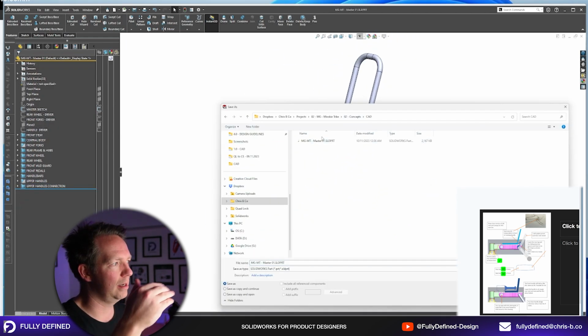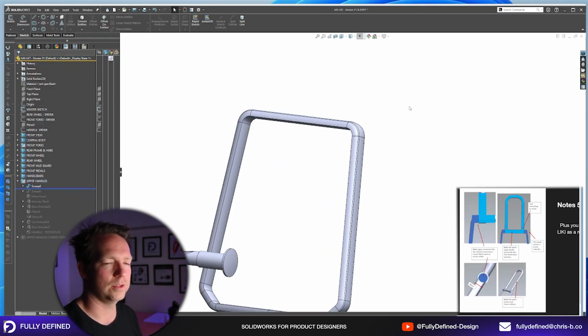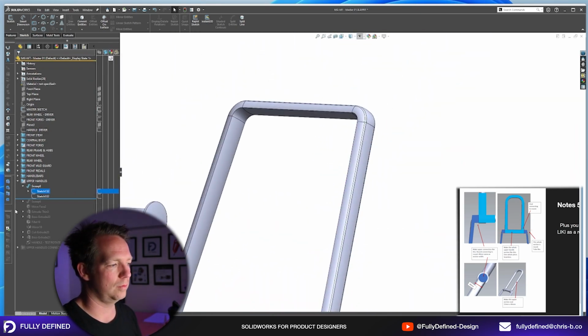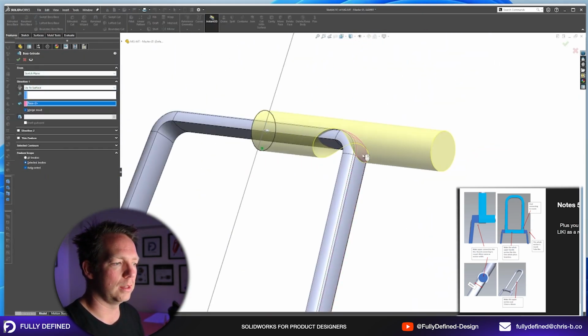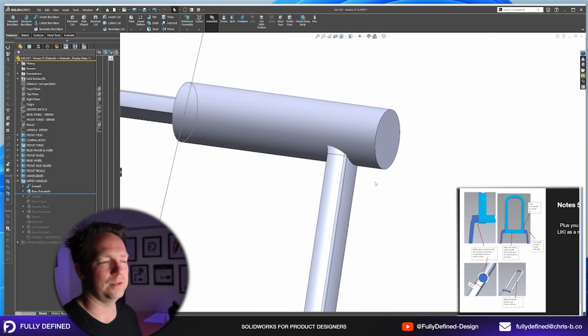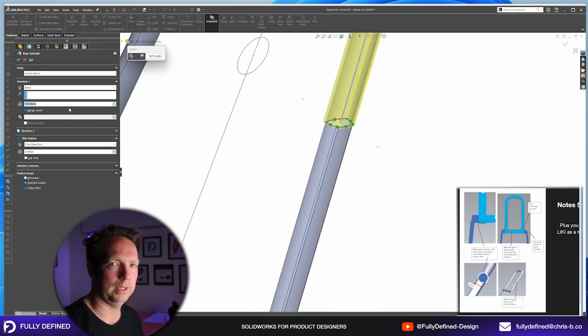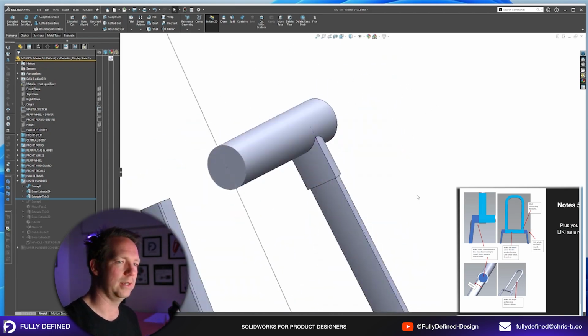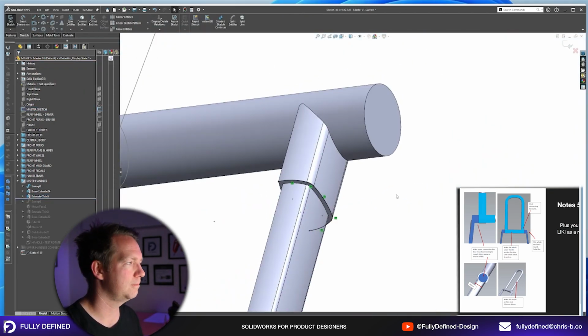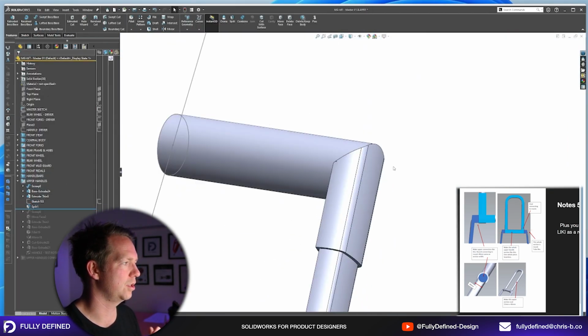The last step in that, go back to those features and just redo the references that they're built from. So instead of being referenced from something that you've modeled separately to the master sketch, delete those relations, reference the master sketch. I think I'll show that in another video.